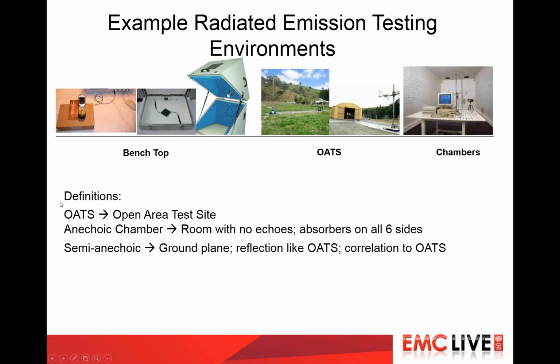Different environments you can test in. I've seen testing on benches. There are TEM cells out there, which is a shielded box you can put a device in to test. You can have an open air test site where you can do testing outdoors. Again, you need to record your ambients and then eliminate them from the testing with a quasi-peak detector.